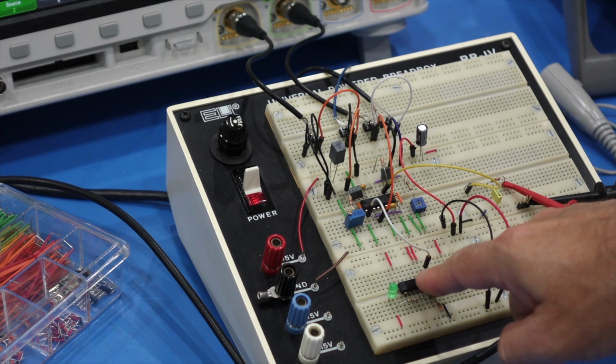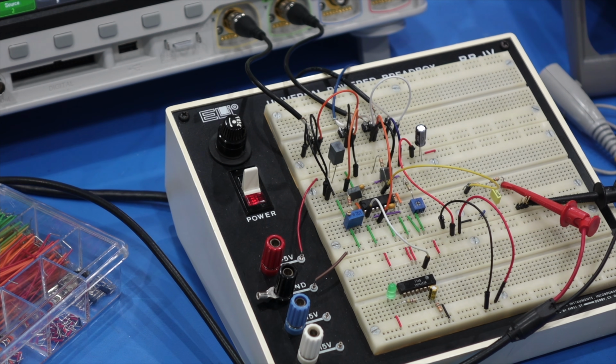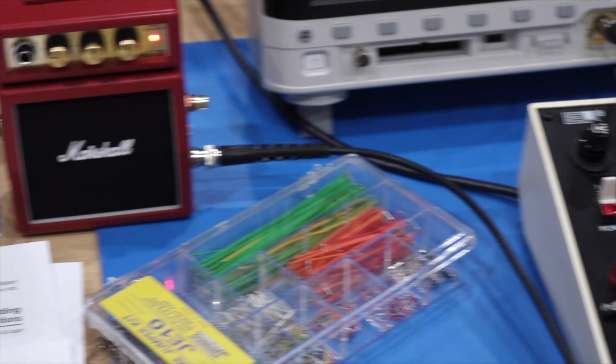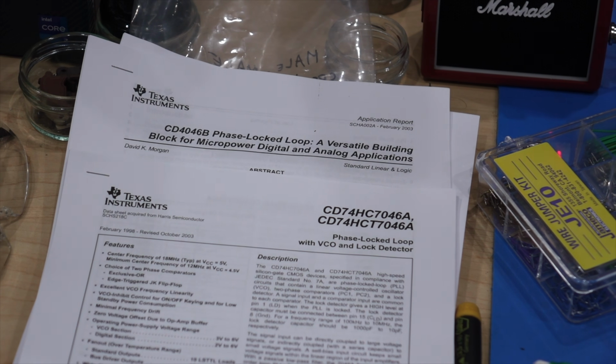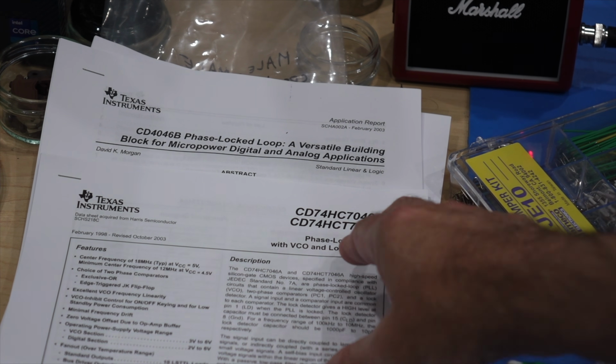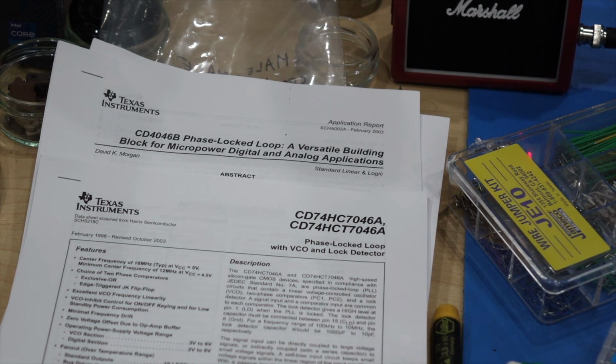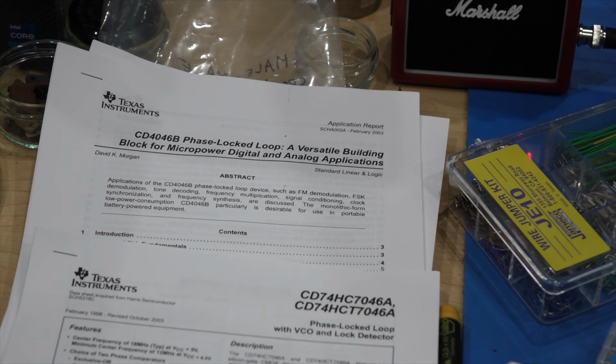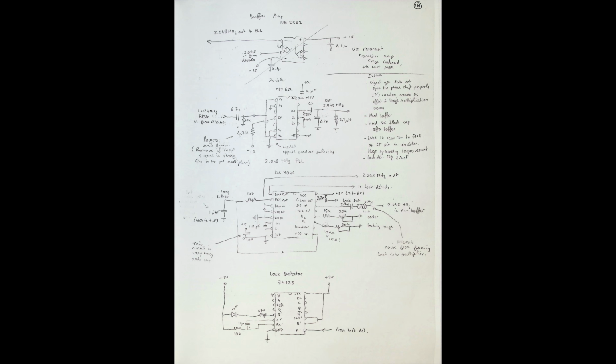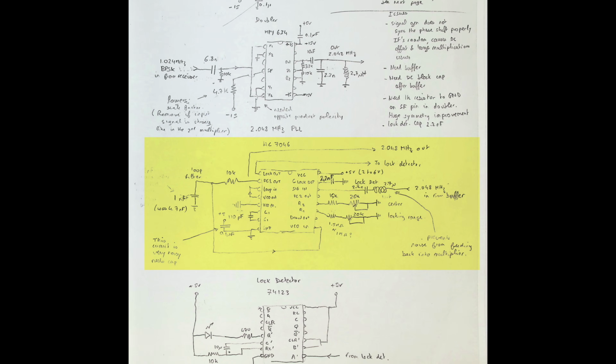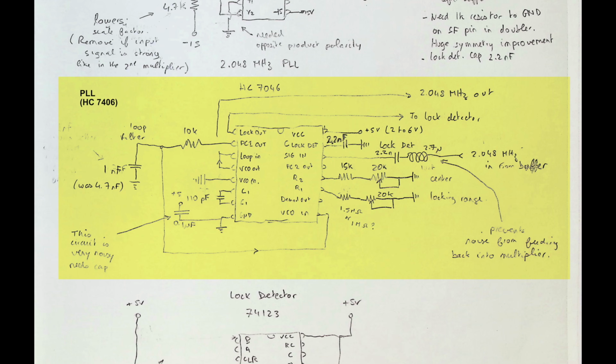This PLL circuit is an old friend. That's the very one we had used in episode 30 to make the down voice FM decoder. It's a very good, very old circuit, still made today, but with a remarkably bad data sheet. Nevertheless, now that I have the hang of it from our previous project, I quickly got it to lock on the squared signal. Same thing, couple resistors and caps, and in the designer of the circuit we trust.